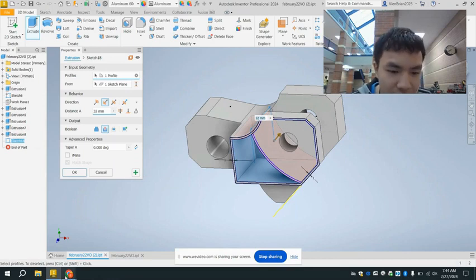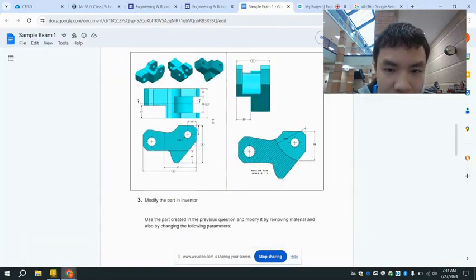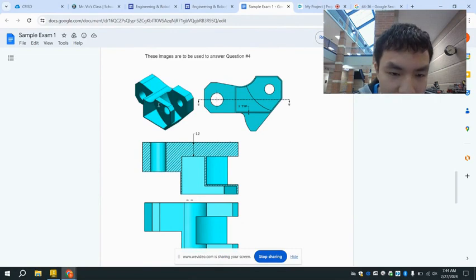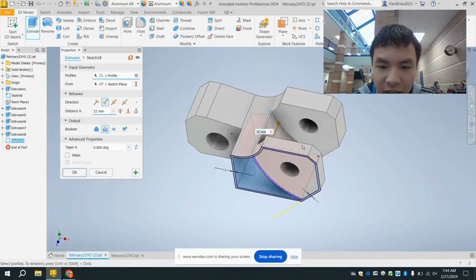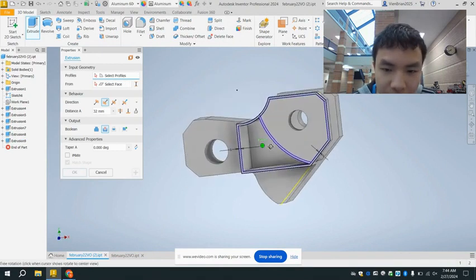So we have that now, but also here, this is also extruded back. And for this one, you can still see the circle. So what I did, you can just keep on extruding so you all see the circles. Let's say this piece is 8 millimeters, right? So obviously you can't extrude more than 8. So let's do that. So that's 32. Extrude that. Should give you that.